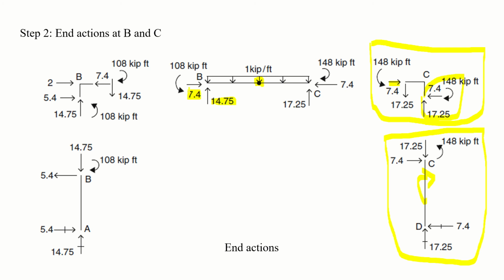So you have satisfied two equations, summation of Fx and summation of Fy, and you have applied the remaining forces at the other end, for example at end B. Okay, now you are left with only one thing, and that is summation of moments. Now, as I told you repeatedly, and I'm telling you again here, that all the moments at this point will be zero. This means that this bending moment and moment due to this load or shear force cannot be transferred across this point E. Okay, so all the moments should sum up to zero at this point.